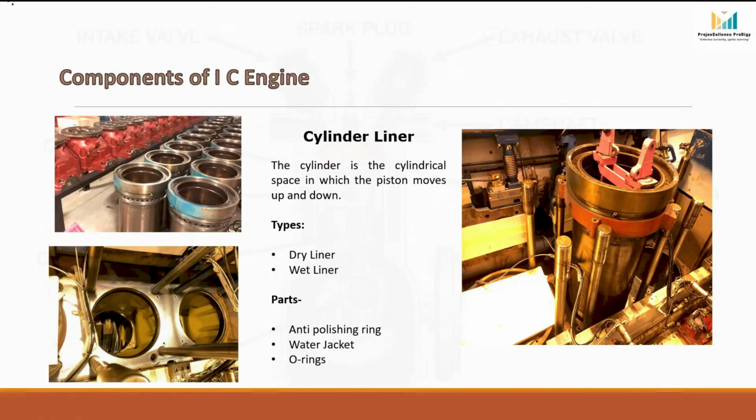The second type is the wet liner. In a wet liner arrangement, the outer surface of the liner is directly surrounded by cooling water. Because of the direct contact with coolant, heat transfer is much more effective and liner cooling is significantly better.